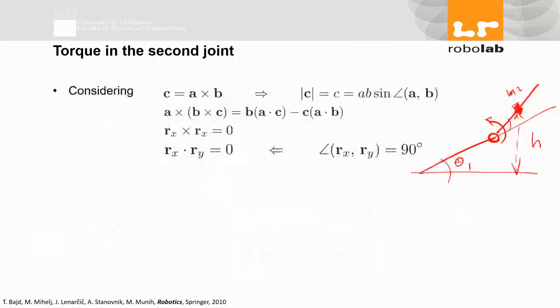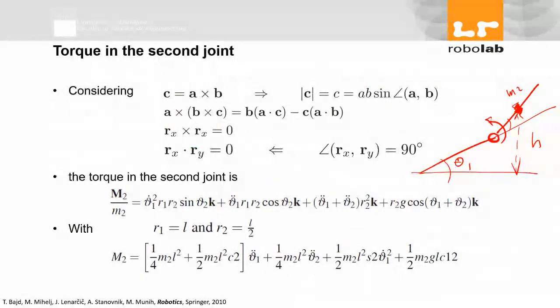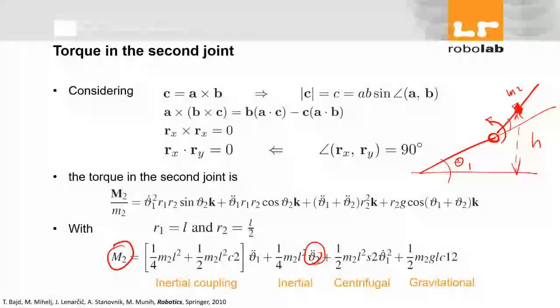On the other one, here, you see, talking about torque at motor 2. When I have the second derivative of theta 2, it's inertial. So this motor is affected by the inertia of this one. But I also see the second derivative of theta 1, which is related to the first link. We call that inertial coupling of 1 over 2. That's the reason, you see?